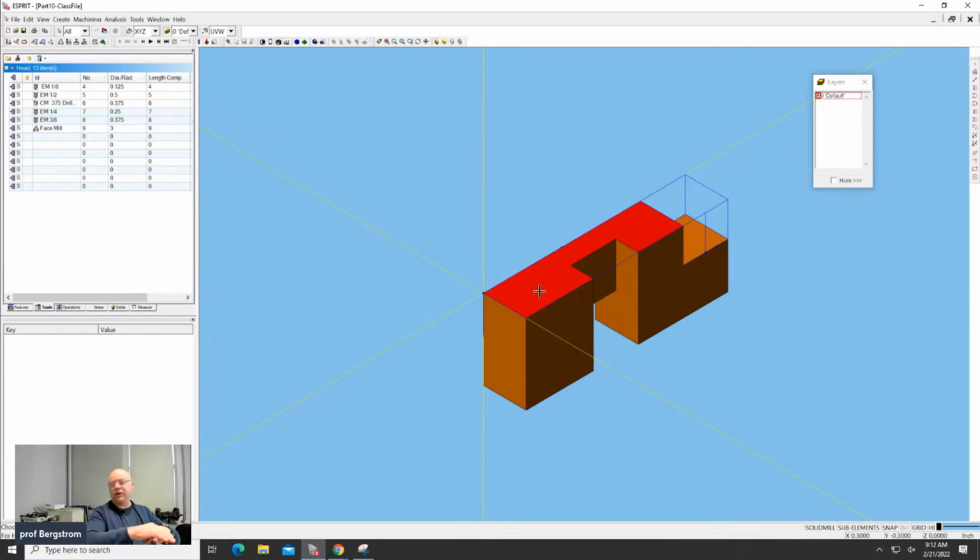So often I will purposefully have the stock be a little bit taller than the workpiece. When we set up the machine, it's easy to probe the top surface of the stock. The easiest way to do that is to shift the workpiece down a little bit in Z in the CAM software so that the stock is aligned with the top.